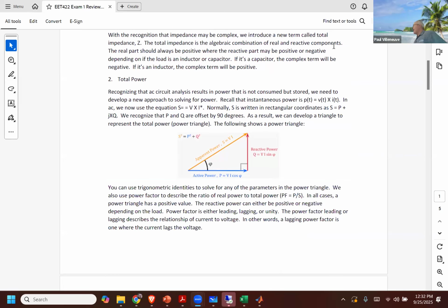And the power triangle is always a right triangle. It's always going to be in quadrant 1 or quadrant 4. When I talk about quadrants, that's the graphs here, where we're looking at quadrant 1 or quadrant 4, the regions in our XY Cartesian plot. And it's always going to be in 1 or 4 because our real power is always positive.